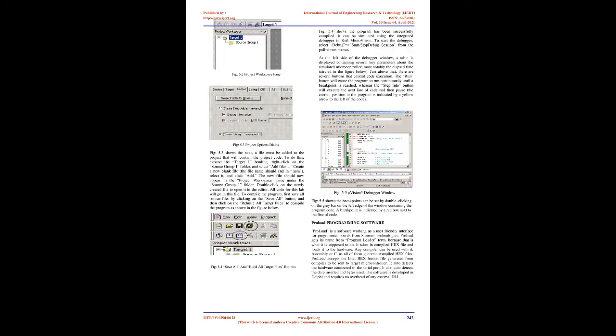These ICs are used when driving a wide range of loads and are used as relay drivers, display drivers, line drivers etc. ULN 2003 is also commonly used while driving stepper motors. Refer to stepper motor interfacing using ULN 2003. The zero crossing feature of the triac driver, an opto-isolator, ensures low noise generation, thus avoiding sudden inrush of current on resistive and inductive loads.